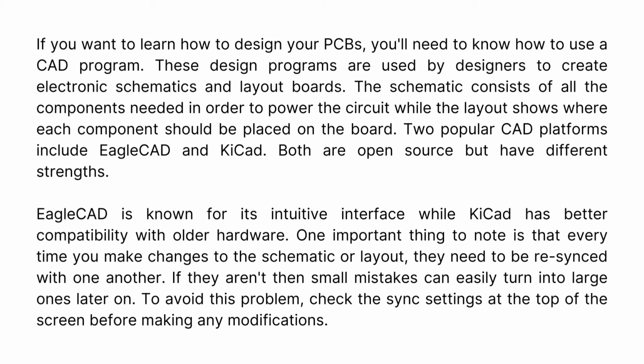One important thing to note is that every time you make changes to the schematic or layout, they need to be resynced with one another. If they aren't, then small mistakes can easily turn into large ones later on. To avoid this problem, check the sync settings at the top of the screen before making any modifications.